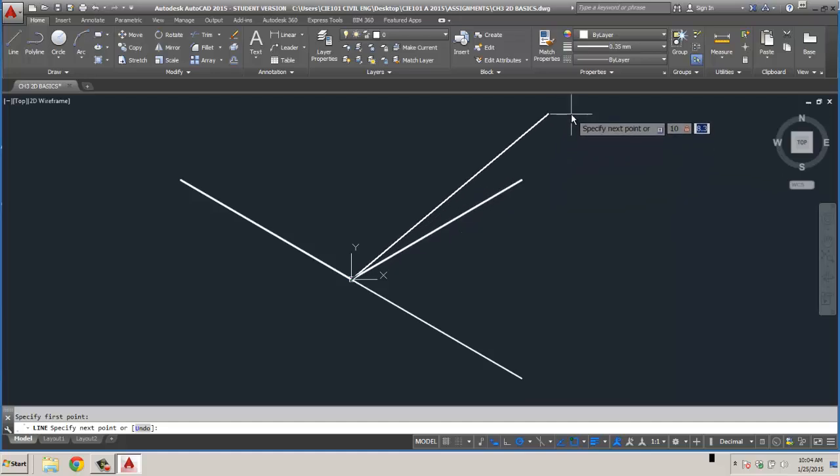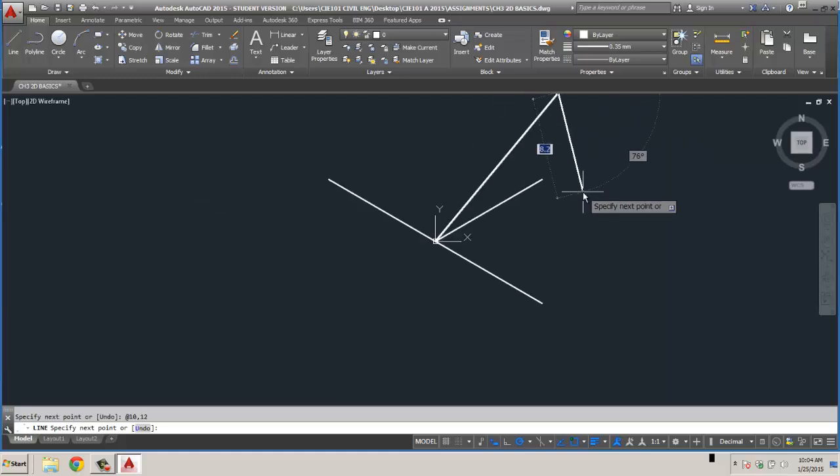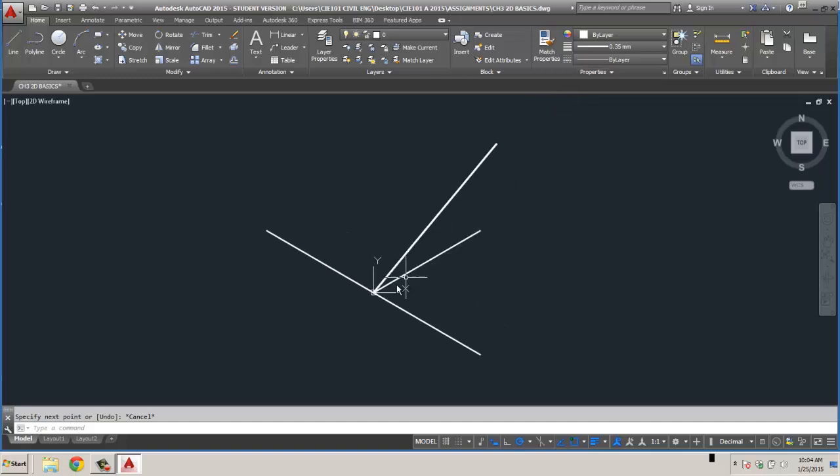You can see it lengthens the line because it's just set at 10 here. But as I pull it up, I'm locking into this y-axis. So if I want to make this, let's say, 12, it's over 10, up 12. Hit enter, and there it is. So that doesn't necessarily make the line of length 10. It just gives you 10 in the X mode and 12 in the Y mode. Now, starting from this endpoint, let's just start a line from here.